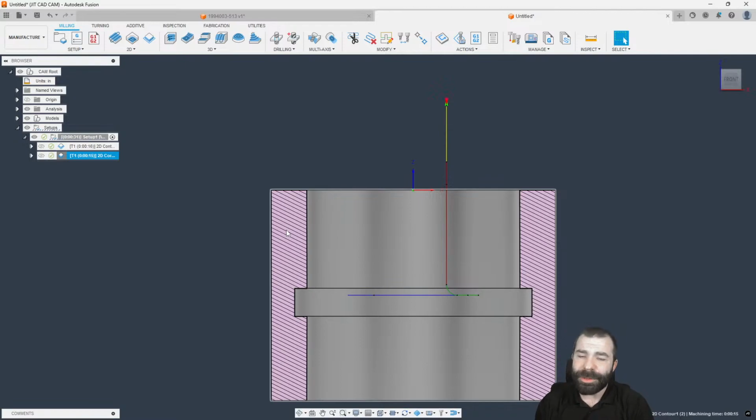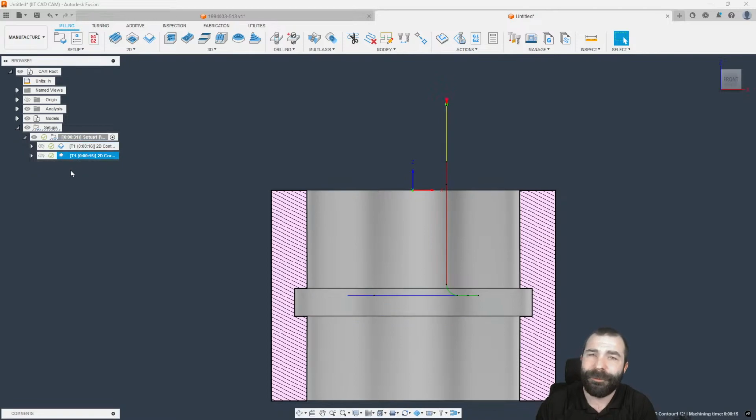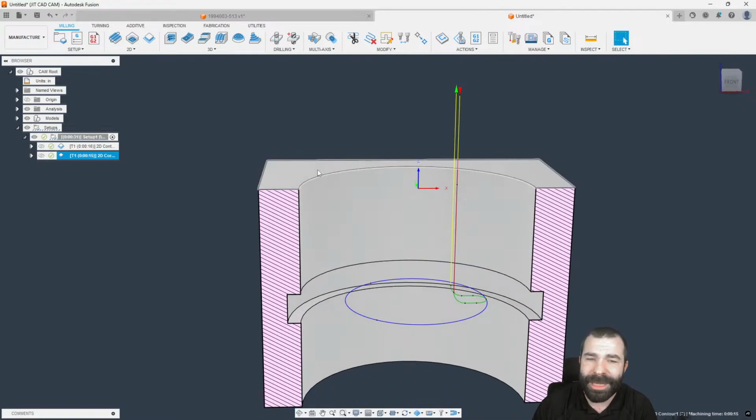Now, when I do an O-ring like this and my tool isn't perfect to size, I still like to set an upper and a lower finishing pass. What that allows me to do is to really control the width of that O-ring groove independently, right? Again, when you send this off to QA and they don't want to measure it or they don't measure it correctly, you can adjust and accommodate to them, right? But now there's some other ways to do this.